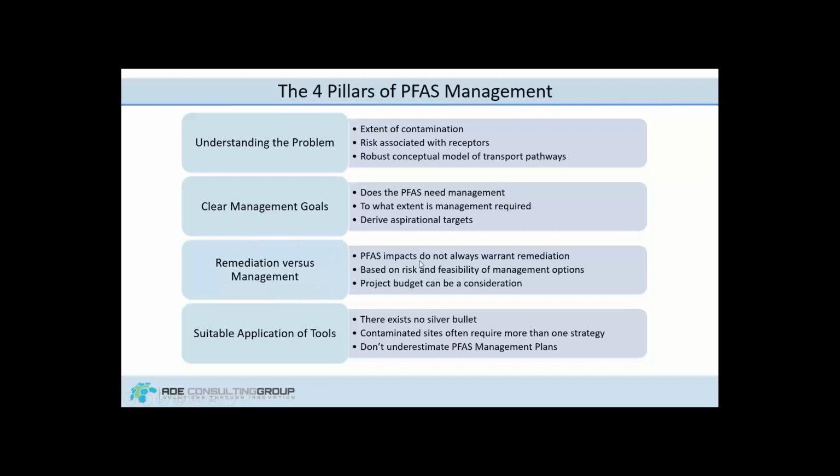Again, remediation first management, basically comparing whether we can achieve that target just through management practices, or if there really is a need for remediation. And then lastly, something we don't often look at is feasibility. While there's remediation technology out there, if the PFAS plume, for instance, is in the CBD under a number of buildings, digging up the soil and treating it might not be a possibility, and that may then defer us to other technologies that we have to use, such as pump and treat. So it may be decided for us which application we have to use. Further to that, obviously there's budget considerations, but we won't go too much into that.